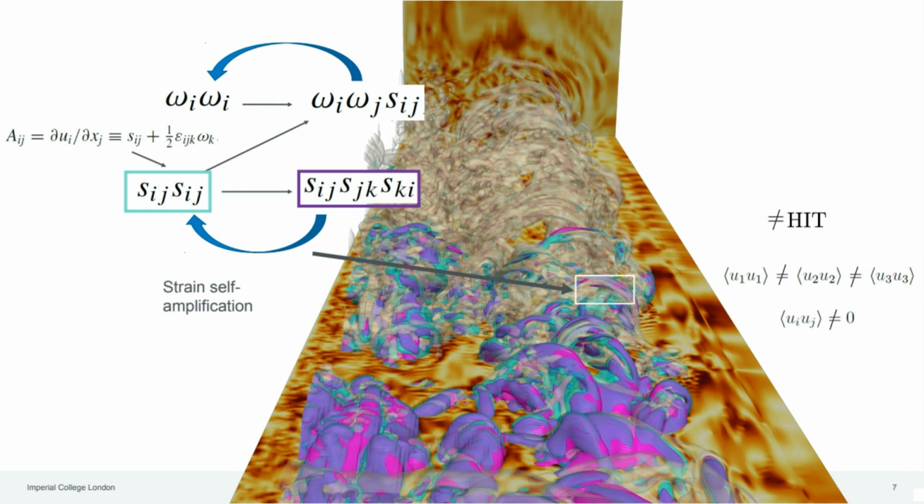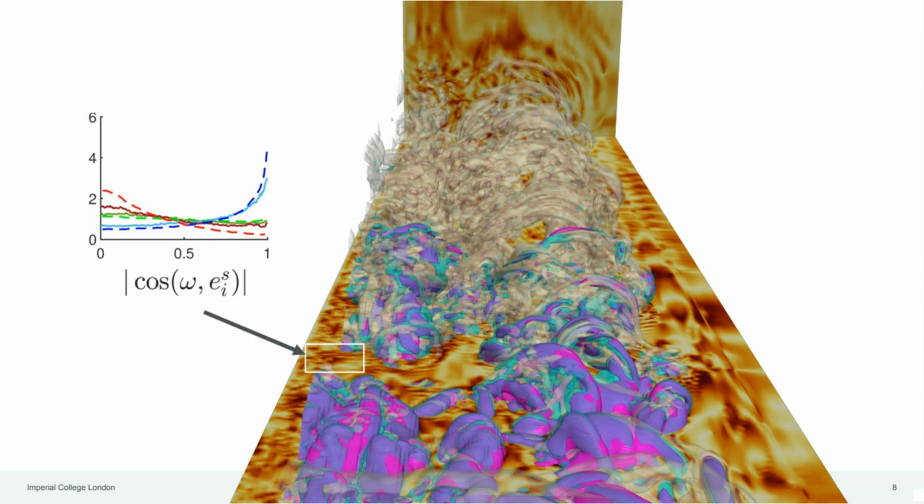Just to conclude my last slide, which has to do with the title, what I call this chaotic sea, is actually, despite the high disorder that it might show, there is a lot of coherence in certain points of the flow. For example, in this display, in this yellow contour, I'm computing the alignment between vorticity and the strain rate.